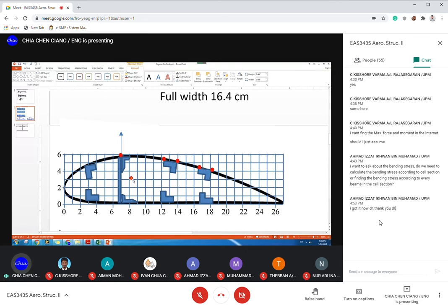Okay, let's say this is the centroid. Yes, upper. And doctor, that's the center of the whole airfoil, right? Yes, the center of the whole airfoil. Then I expect that the stress will be maximum near some point far away from the centroid, right?